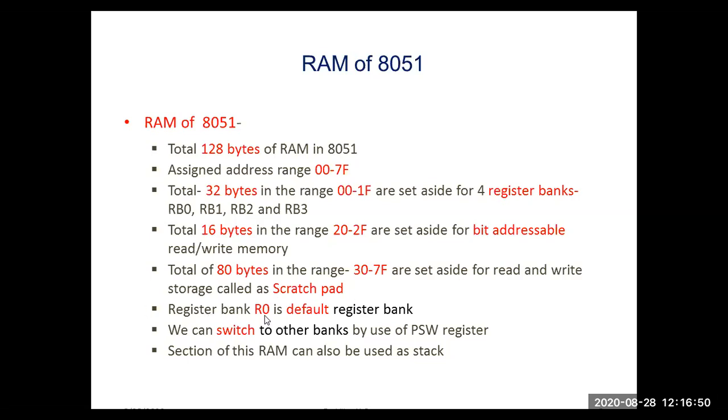Register bank RB0 is default register bank. We can switch to other banks by using one of the special function registers, SFR, that is PSW SFR. Okay, a section of this RAM can also be used as stack.